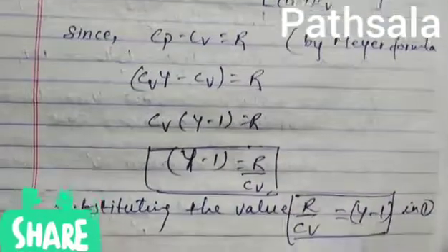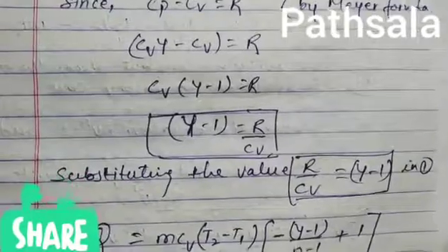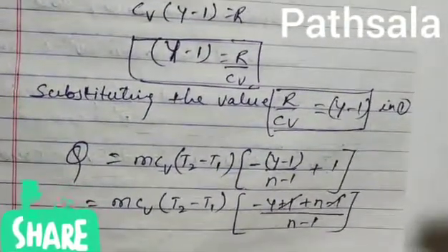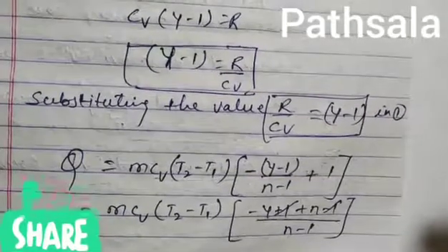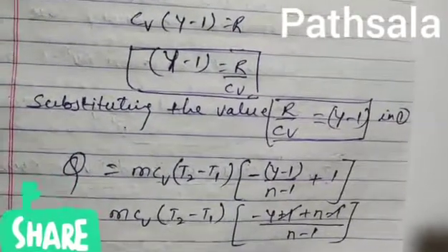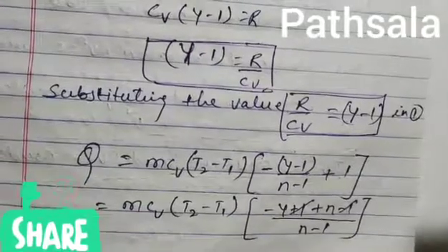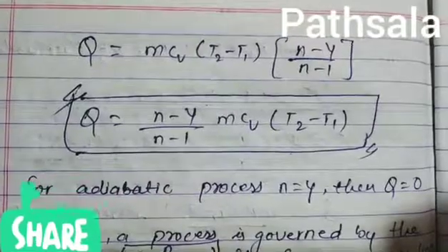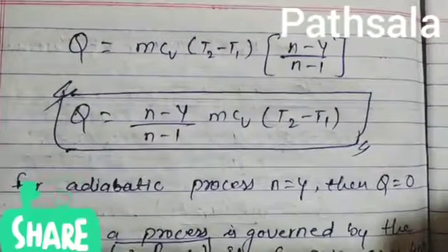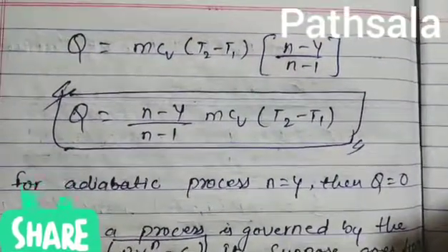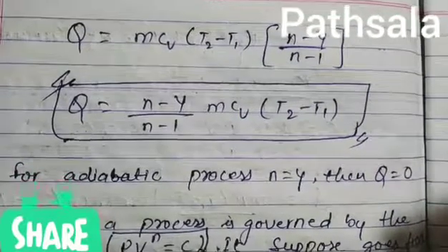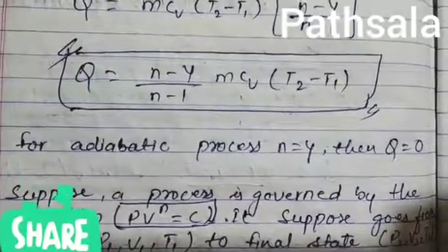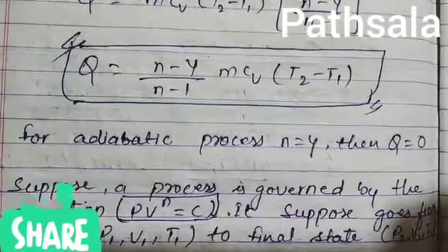As you can see, gamma minus 1 is equal to R upon Cv. We put gamma minus 1 in these values and we get Q is equal to m Cv (T2 minus T1) in brackets, (gamma minus 1) upon (n minus 1) plus 1. We get Q is equal to m Cv (T2 minus T1) bracket (n minus gamma) upon (n minus 1). Q is equal to (n minus gamma) upon (n minus 1) times m Cv (T2 minus T1).